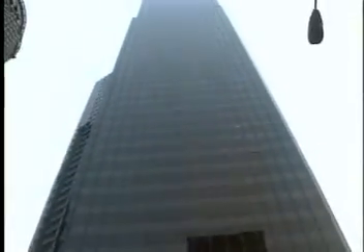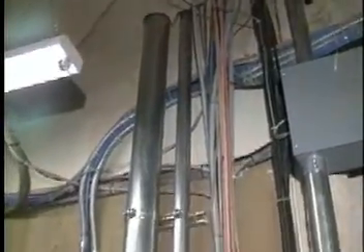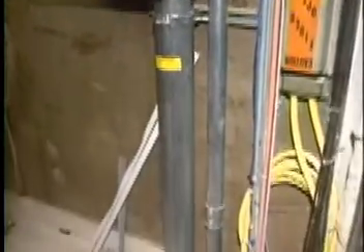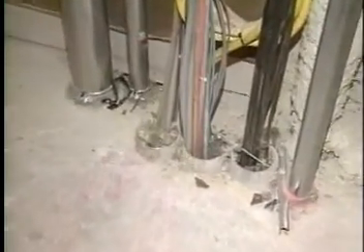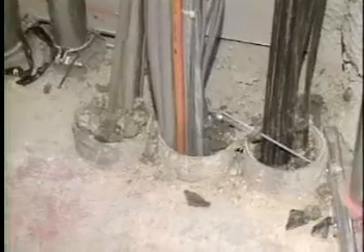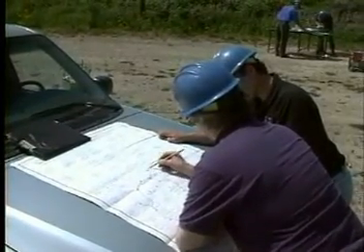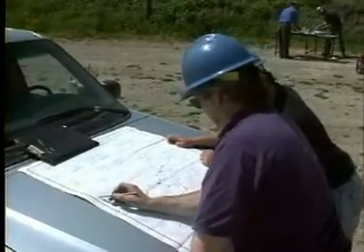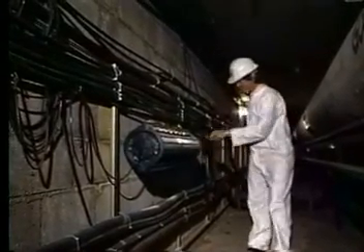Riser cable must be capable of withstanding the stresses of its own weight. The maximum vertical rise is the maximum length of cable that may be mounted vertically without strain relief. It is recommended that the cable be tied off at least every 2 floors to limit stresses due to cable weight. Always follow prescribed laws or building codes and keep accurate, as-built diagrams of the installation complete with footage markings on the cable to assist with future expansion or restoration efforts.